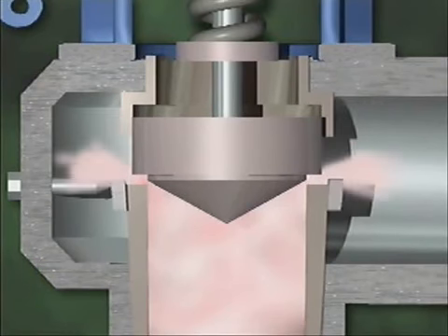If the adjusting ring is lowered, it's easier for the steam to escape to the side of the disc, so much less escaping steam strikes the disc on its way to the valve outlet. The velocity of the steam exerts less upward force on the disc, and more system pressure is required to hold the disc open. So with the adjusting ring in the lowered position, the valve closes against higher system pressure than it did when the ring was raised. Lowering the adjusting ring, then, decreases the blowdown of the valve.